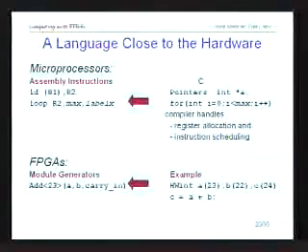Doing the same thing for FPGAs, now we don't have an instruction set. Instead of an instruction set, we have module generators. So basically, we have a huge number of instructions. Any module that we possibly could get our hands on, we gathered into our little database. That's our instruction set. And we're trying to map an application down to this particular instruction set that is limited by the amount of modules that I have in my module generation environment.